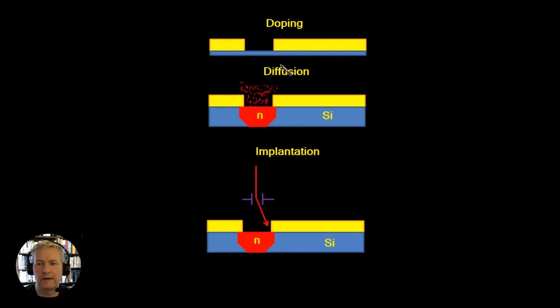So now within the silicon layer, we can diffuse the silicon, or we can implant the silicon to create these N-type or P-type wells. So the process of diffusion or implantation are just 2 different methods of creating the well. In diffusion, we have a gaseous material which diffuses into the region.